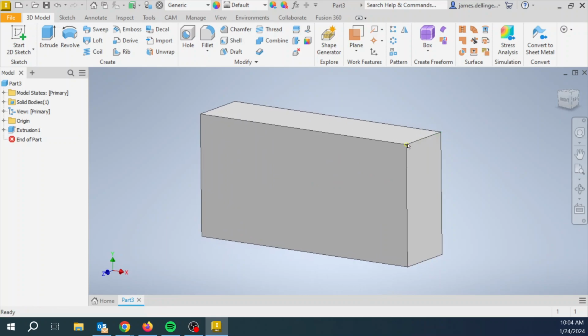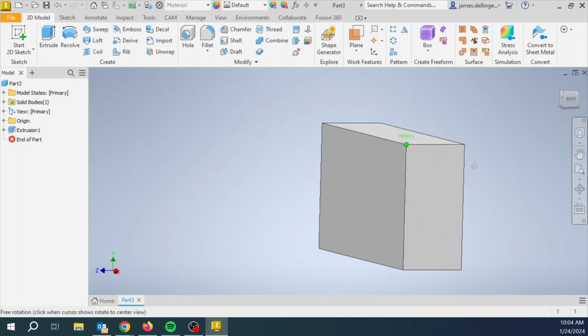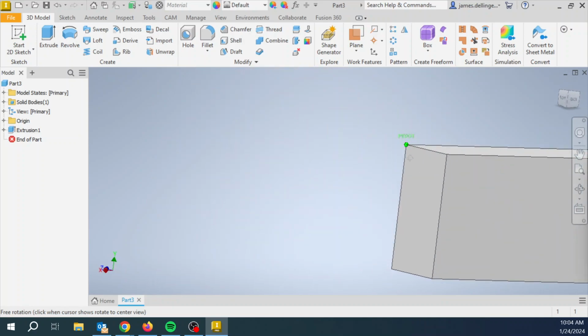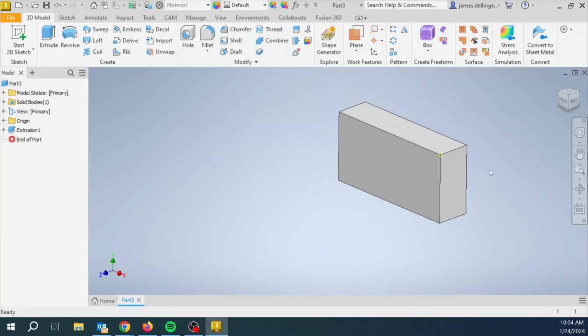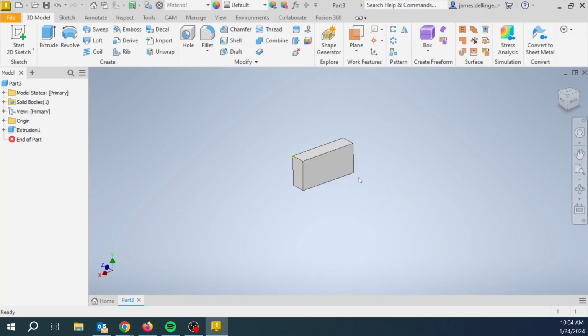well. If you pre-select, I'm going to pre-select that corner and then middle mouse, and hold the shift key. You want to press the shift key first and then hit the middle mouse. Then it's going to pivot around the part that I selected. All right, so then you can combine those three to get everything that you want to do.